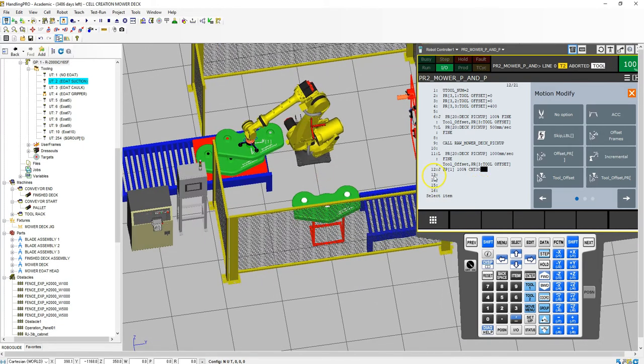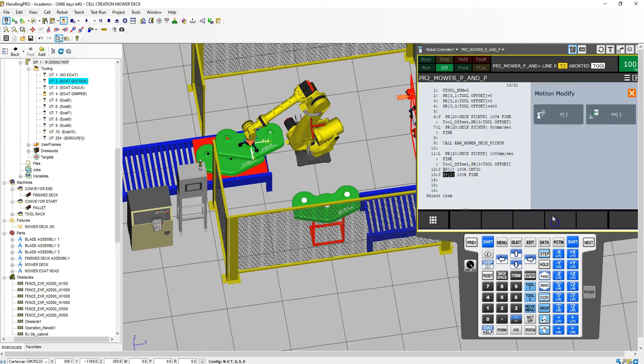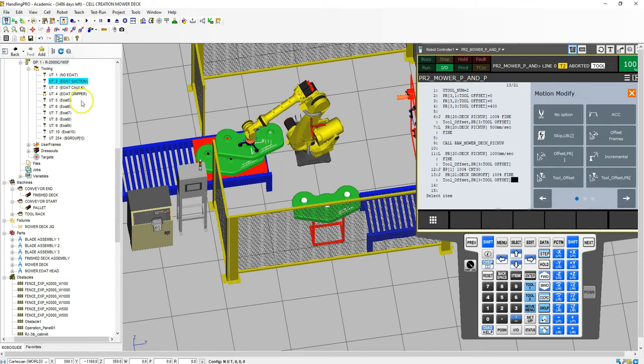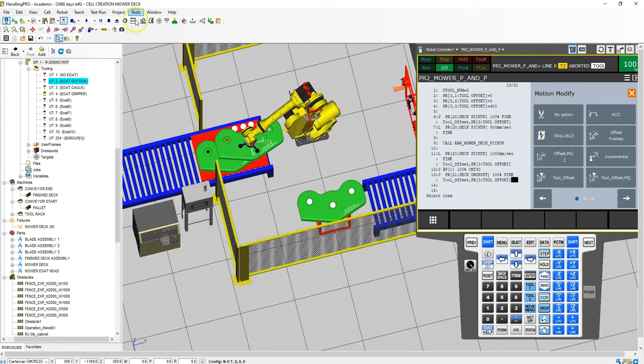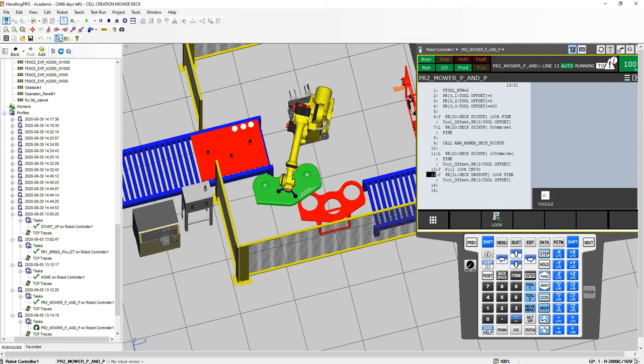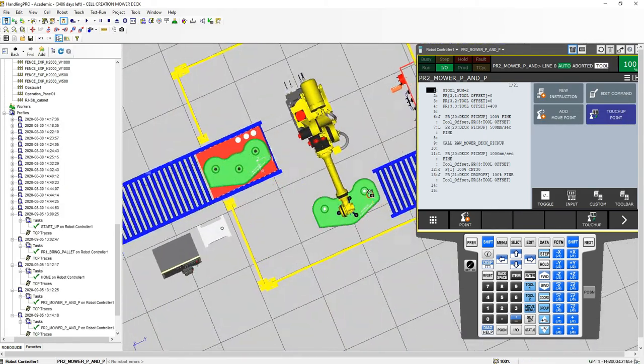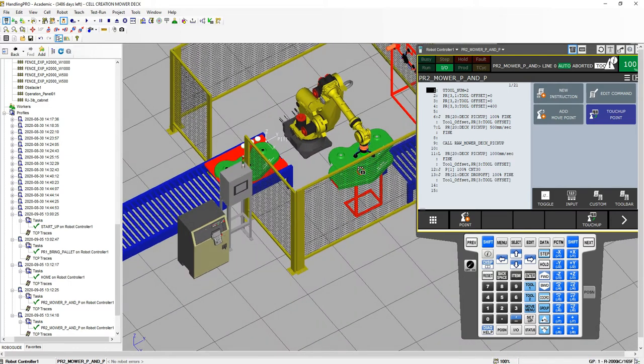Okay, so we're going to continuously move to the next position with a joint movement to our position register number 21, which is the drop-off area with the offset. Tool offset number 3. So let's check this out, make sure it's not running into the rack here. We just run this from here. There we go. So notice how it moved in and then over very quickly, all the way down.